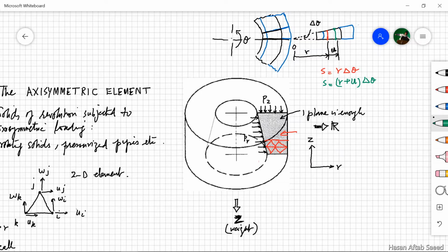The point to understand here is that the particles of any two planes must remain on their respective planes. So if a point moves in the radial direction, like we saw 2 points in red occupy the position shown in green, then this necessarily produces an extension in these arcs, and that extension, because it is in the circumferential direction, causes the strain epsilon theta, that is circumferential strain.